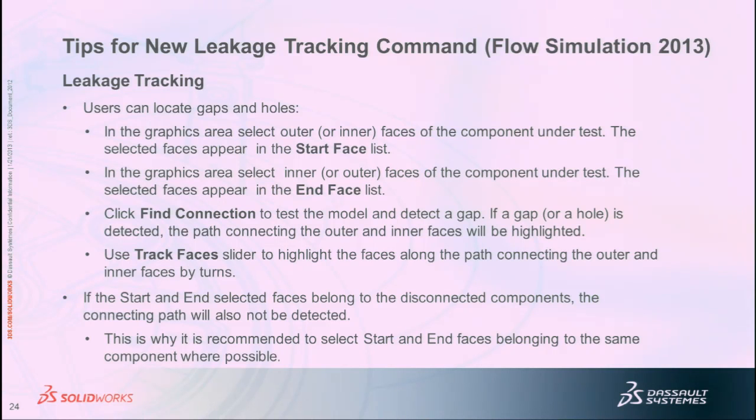You can do a cross-section and rotate it and try to see if you can see space on the other side while you're rotating it. You could create a fluid region using the check geometry command, or a structure. But this new option is supposed to help users find this area. So the leakage means the hole in your geometry somewhere that's preventing flow simulation from creating the internal region.